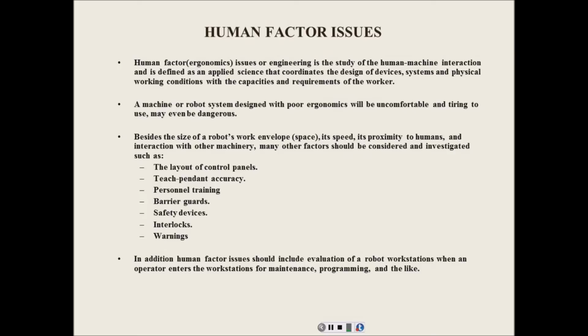But in the Big Fanuc, we don't ever run it. We don't have safeguards on the Big Fanuc. We do have some limiting hard stops on it to keep it from getting into the walls. So that's why basically when we run it, we don't run it. We never run that robot in automatic mode. That robot has what we call a high-speed teach.